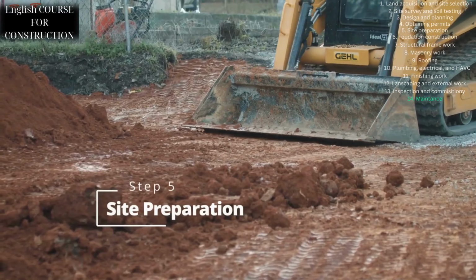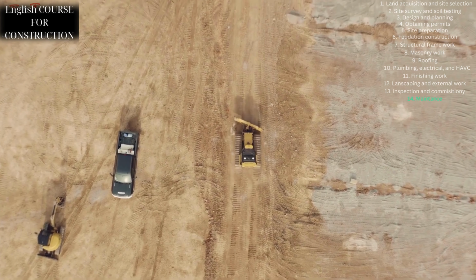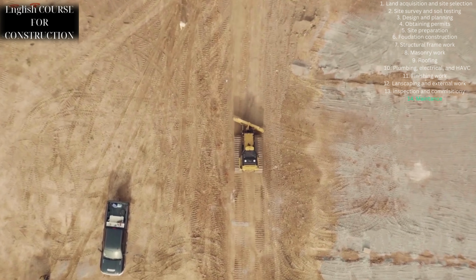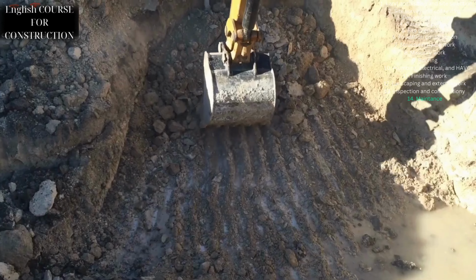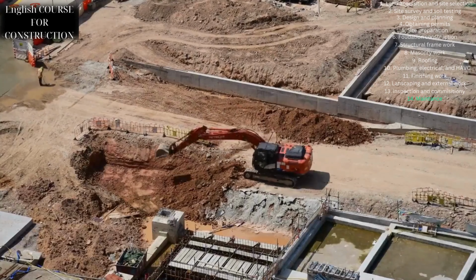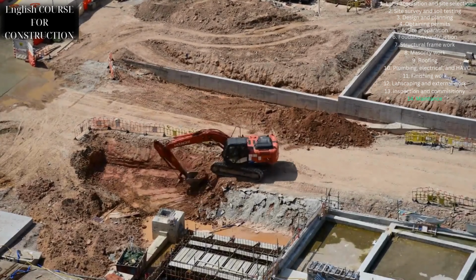Step 5. Site preparation. With all permits in hand, it's time to roll up our sleeves and prepare the site for construction. This involves clearing debris, vegetation, or existing structures and performing earthwork such as excavation and leveling. Proper site preparation is critical to ensure a stable and level surface for our building's foundation.